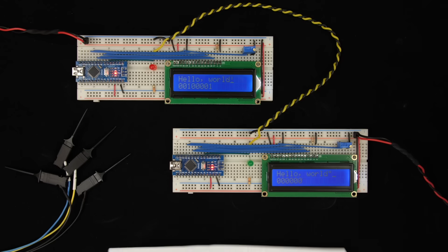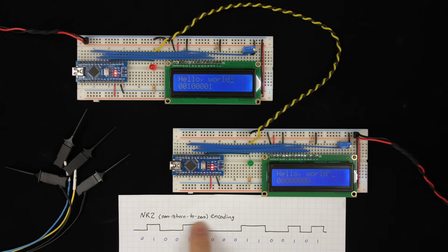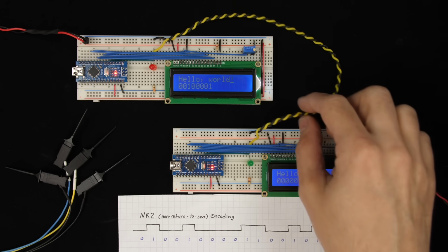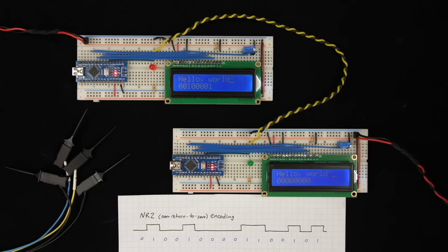So it looks like, unfortunately, we're out of luck if we want to use this NRZ encoding just by itself. Maybe better clocks would help a little bit, but they're only going to get you so far. And actually, as the bit rate is faster, as we send more data faster, then the importance of having those clocks synchronized becomes even more important, because the shorter the time interval between the bits, the more important it is for both sides of this communication to agree on how long that interval is. So trying to improve the clocks is kind of a dead end unless you go for atomic clocks or something,